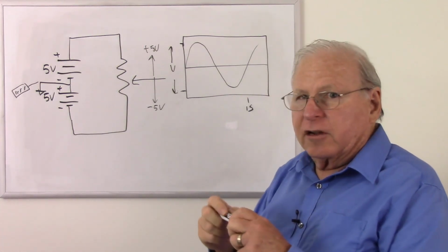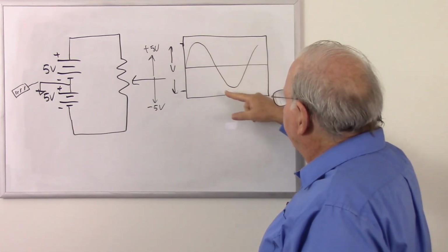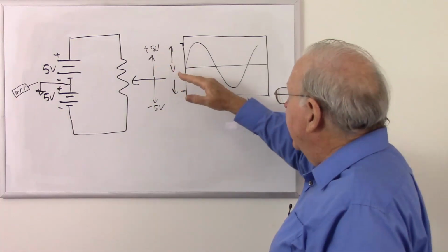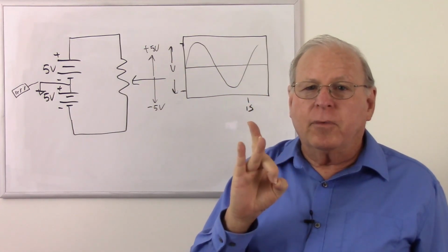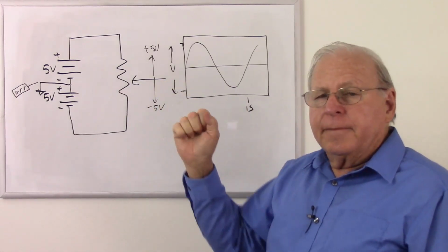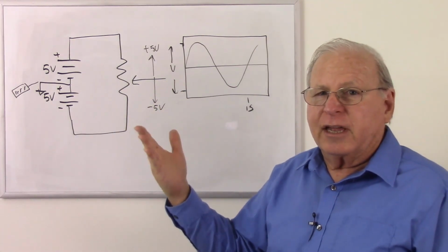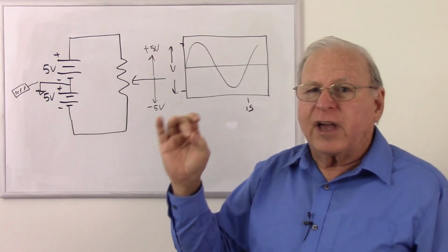We can modify the scale of our oscilloscope to be whatever we really need it to be. And so what we have is this wave. And what's the definition of it? It's a wave that takes 1 second to complete 1 cycle. That is the period of the wave. But as I keep doing that, how many cycles is that every second? Well, it's 1 cycle every second. So the period is 1 second. The frequency is 1 cycle per second.